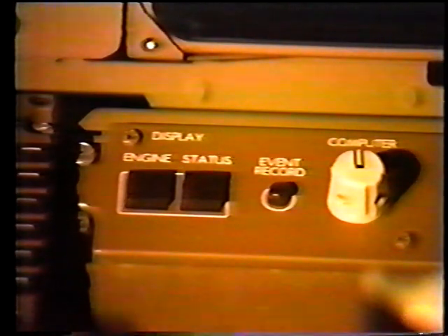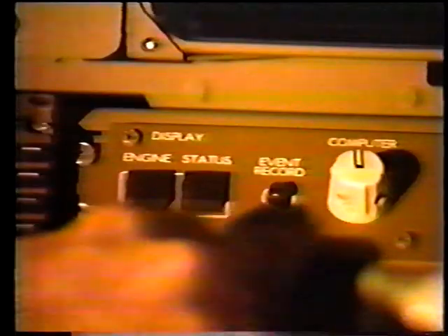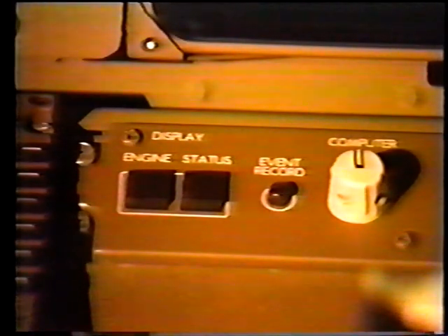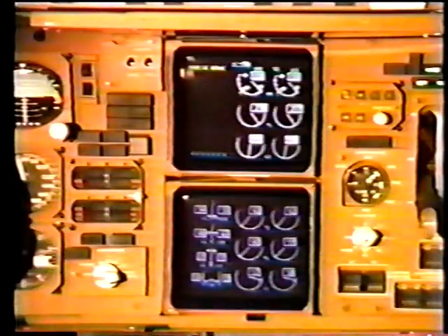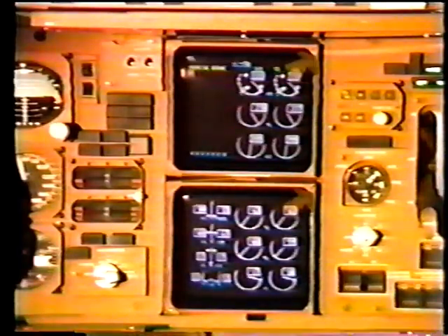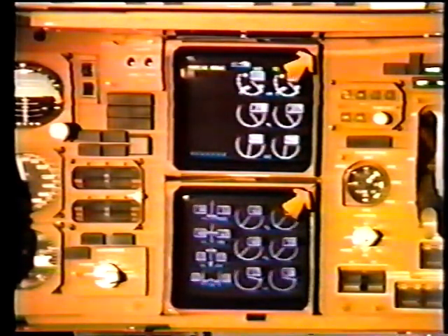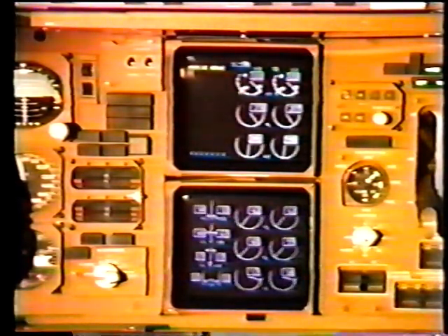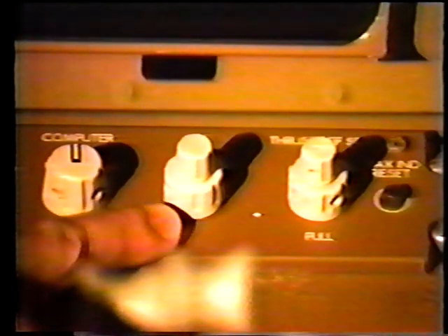for ground maintenance use. The computer select switch in the auto position automatically selects the left ICAS computer as the primary source of information. If it fails, operation is switched to the right computer. Either computer can be selected manually. The brightness for each CRT is automatically adjusted by light sensors located on the CRTs. Brightness can also be changed manually by the brightness control knobs.